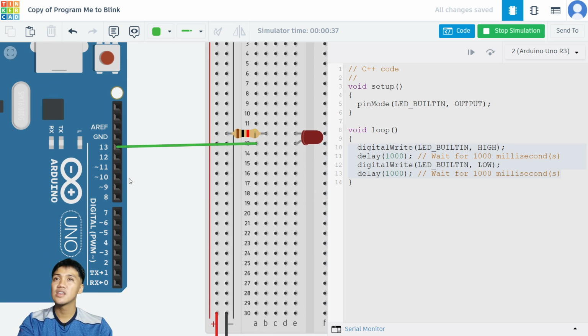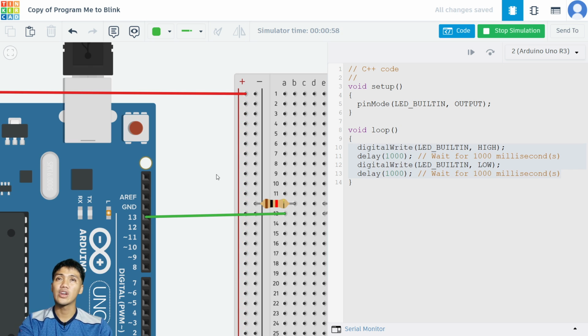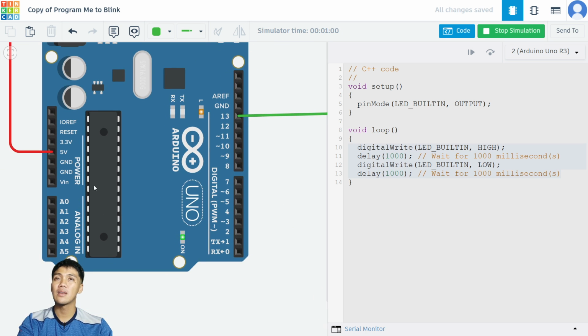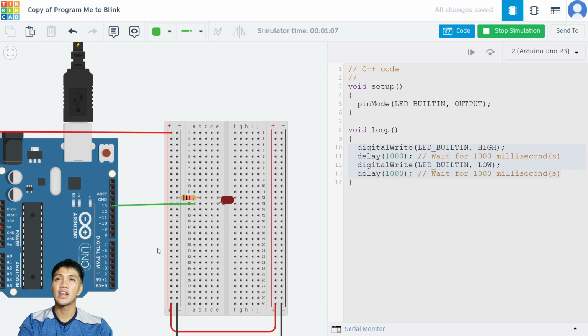In this case, we have voltage. We have a voltage source coming in from pin 13. We are bringing current through this wire and this component rail, and it will go through the anode, cathode, but there is no path, or an unconnected path, towards the ground or ground pin in our Arduino setup right here.